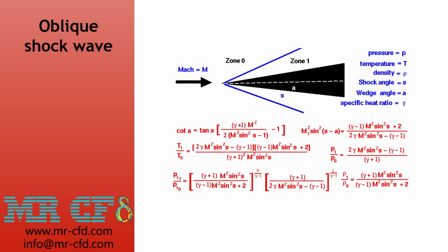There are certain tables describing our Mach number before and after the shock wave based on the cone degree itself and the angle of the shock wave. So what Fluent does is it calculates the pressure distribution along lines on the domain, and by that pressure it can reach the places where we have a jump in our pressure, and it indicates that we have a shock wave there.